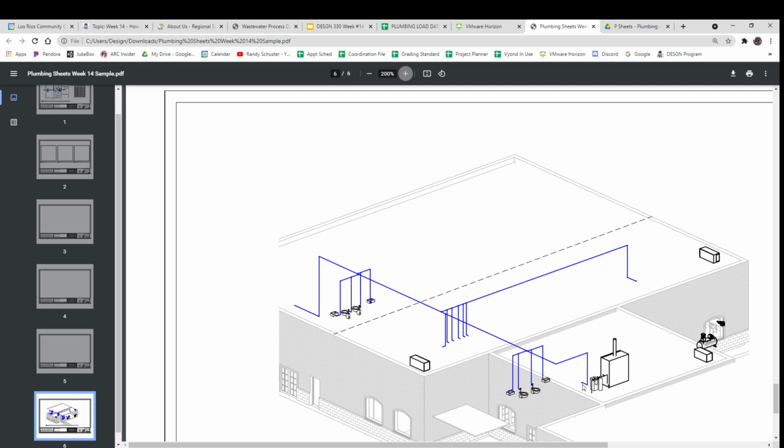So if I want a certain pressure at my hose bib, I have to make sure that I've got enough pressure at the start, and that as the water flows through the piping, I still have enough pressure when I'm done. And that pressure is called the residual pressure. Residual means how much is left. So how much pressure is left by the time water gets here?